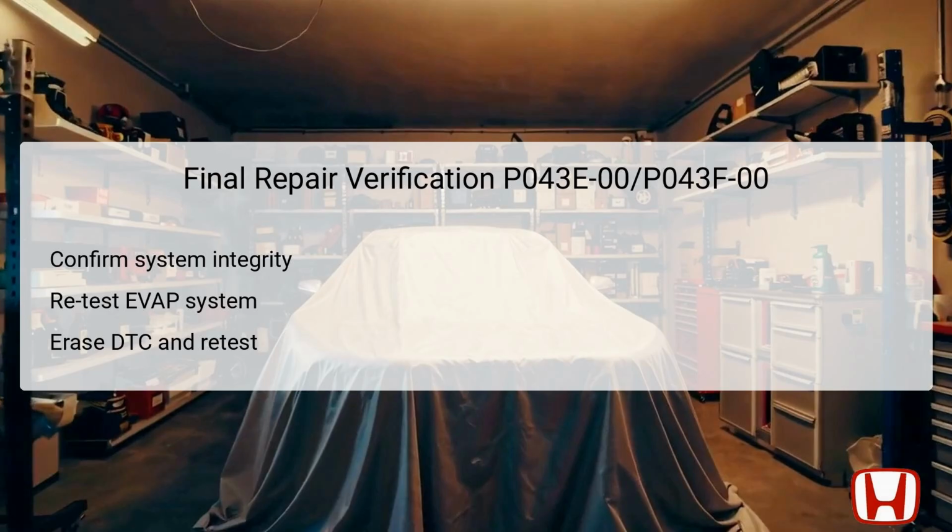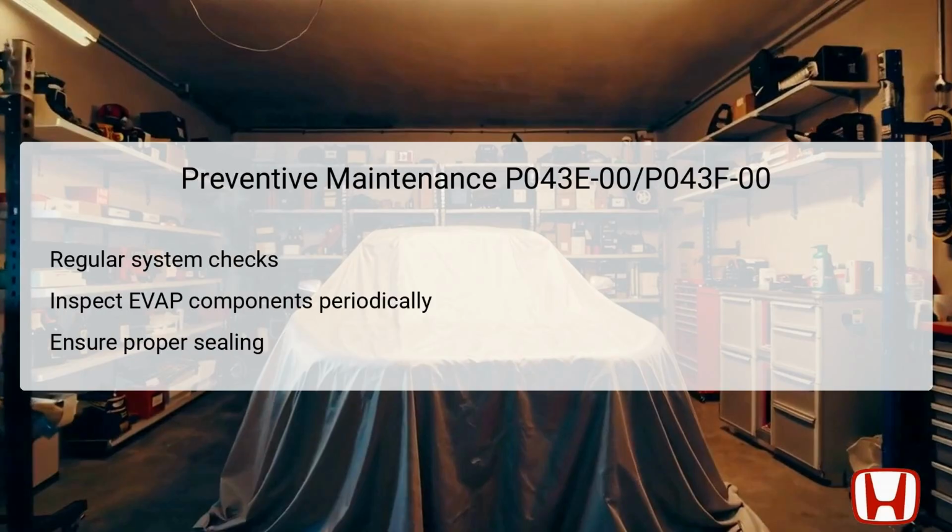If the system passes the tests, resetting the diagnostic trouble codes, DTC, is the next step to clear stored error codes from the PCM. After the DTCs are cleared, it is crucial to retest the evap system under driving conditions to confirm that the issue does not reappear. A thorough final verification ensures that the repairs are successful and that the vehicle will operate as intended in regards to emissions control.